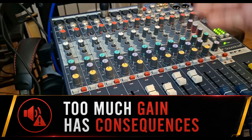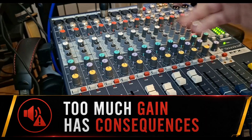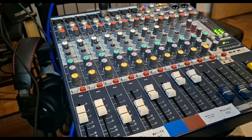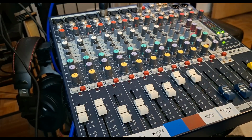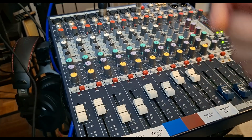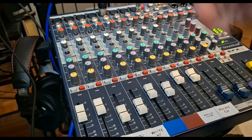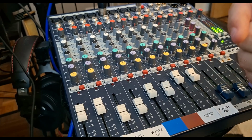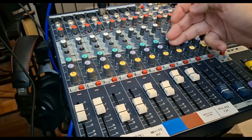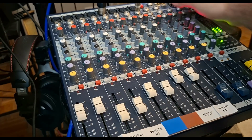It can increase background noise, cause the preamp to clip and distort, make your microphone much more sensitive, reduce your available headroom, increase the likelihood of feedback. Additionally, and this usually can cause a lot of confusion, it can send an overly hot signal everywhere that the channel is routed, including monitors, effects, recording outputs, and of course your main speakers.